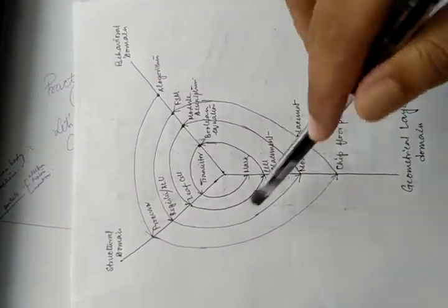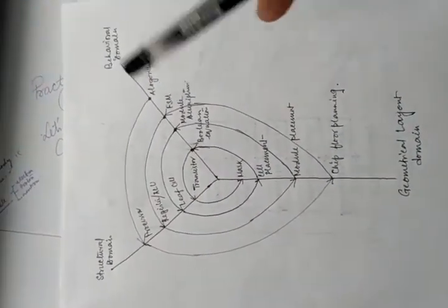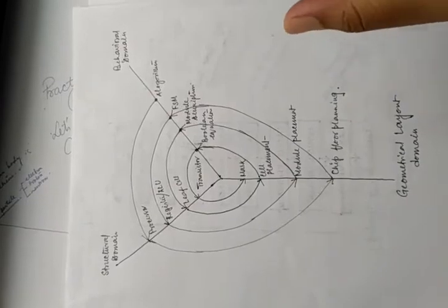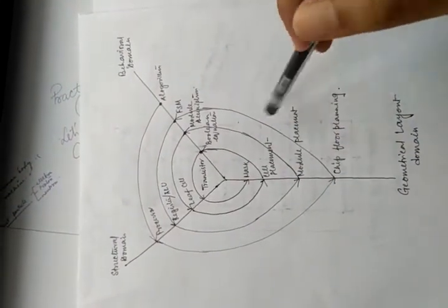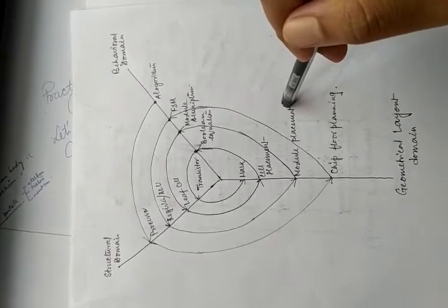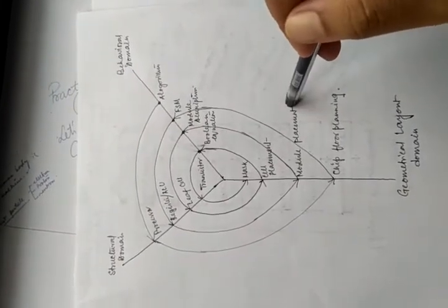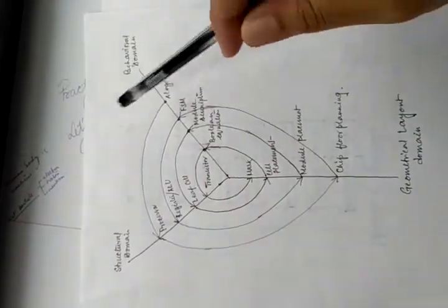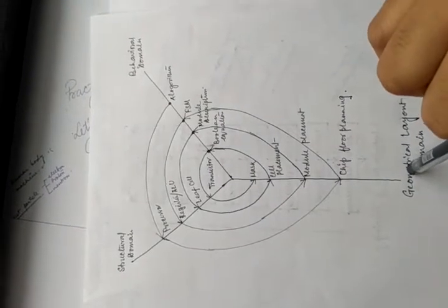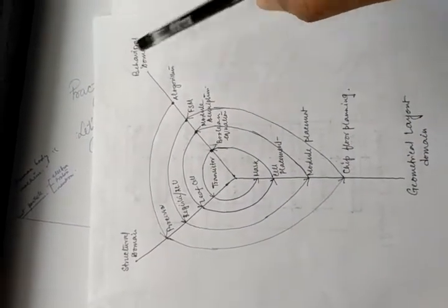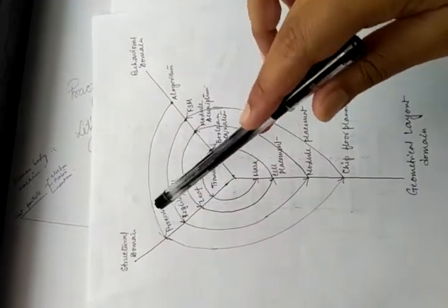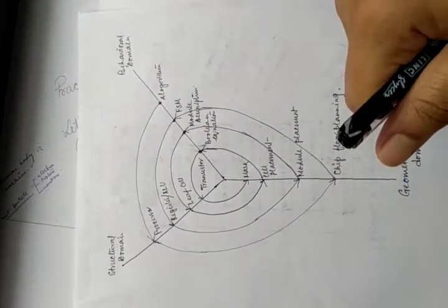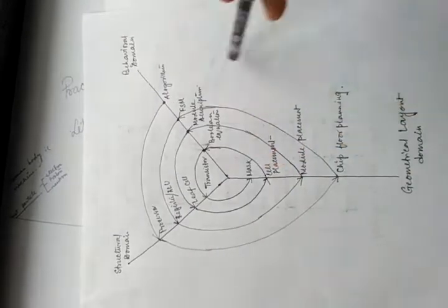these have been generalized in this Y structure, just to give you an idea of how VLSI designing is happening in the industry. This is a very general part, and it is a very important structure. It's the very beginning of your VLSI design flow, and this is a very important question: define the Y chart. Y means there are three domains: behavioral, structural, and obviously geometrical. Because until and unless we know the behavior, we will not be able to develop the structure, and if the structure is not developed, then we will be unable to go for fabrication. So each domain is interrelated with the others.